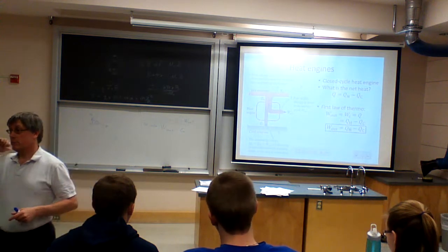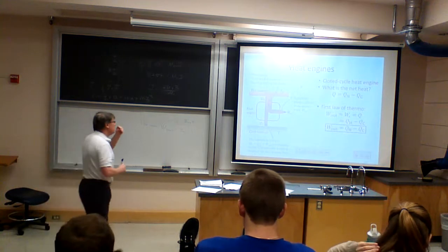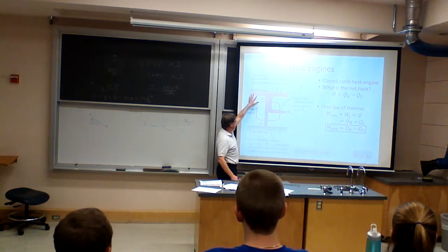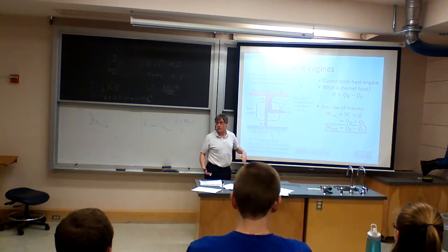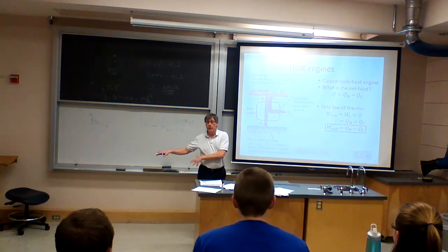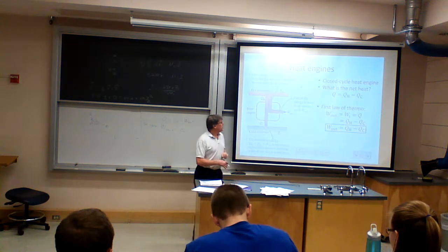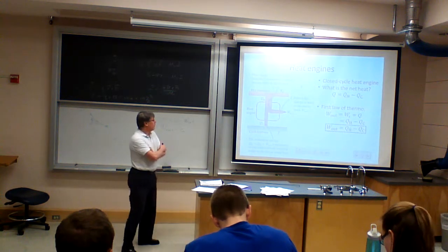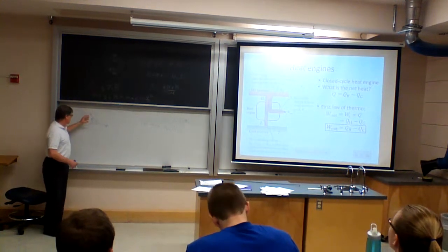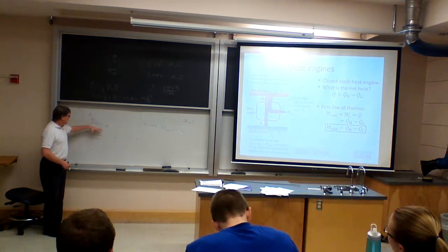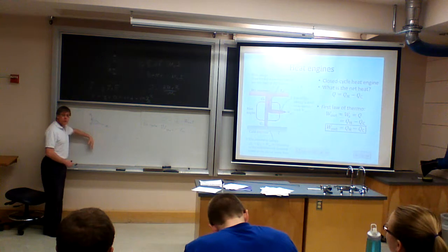Right? When it leaves, it's going out the exhaust. So this would be the temperature of the combustion in your engine. This would be the temperature of your exhaust. Now it says cold reservoir. Your exhaust isn't exactly cold, but that is the temperature that the gas is leaving the engine. So if we measure the amount of heat QH going into the system, the QH hot is going into the system, then Q cold is coming out of the system.